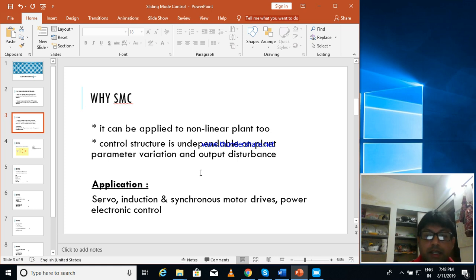Likewise, if you take an example of vector control of an asynchronous induction machine, the quadrature loop tuning is quite difficult, because the natural frequency of the outer loop controller, that is the speed controller, and the inner loop torque controller are in different phase planes. So this kind of thing can be achieved with very high performance dynamic response by the application of sliding mode control.